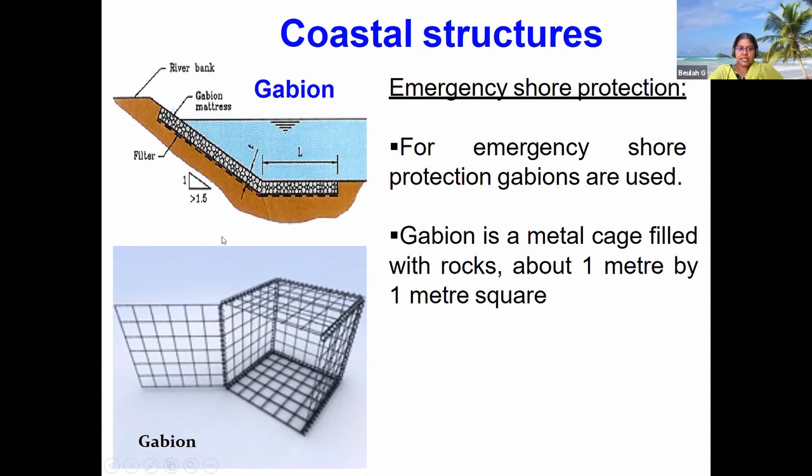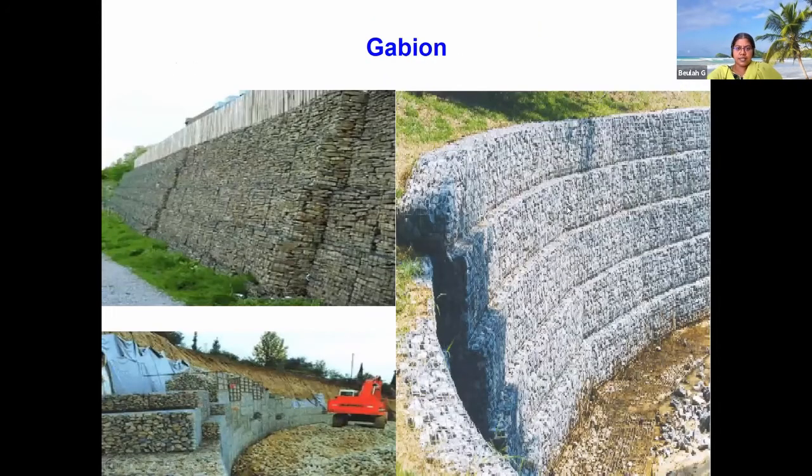So what happens is this gabion has a good interlocking system between each other. This diagram shows how they are piled up. You can see they are not exactly placed vertically, one over the other. There is a small interlocking space, and this interlocking space makes sure that they will not fall one over the other. And here there is an inclined manner of 20 degrees.